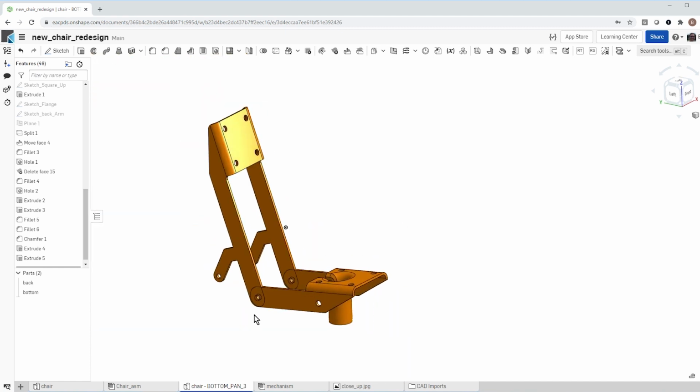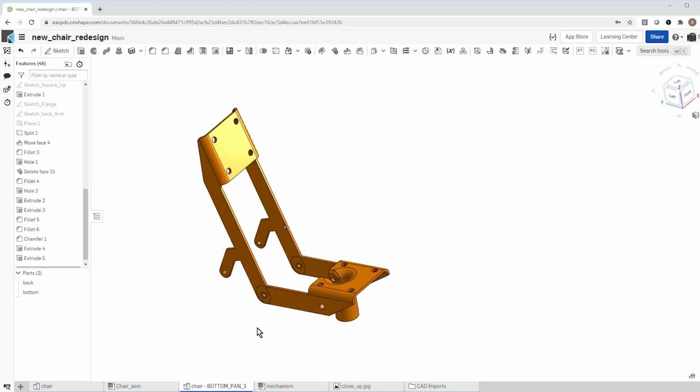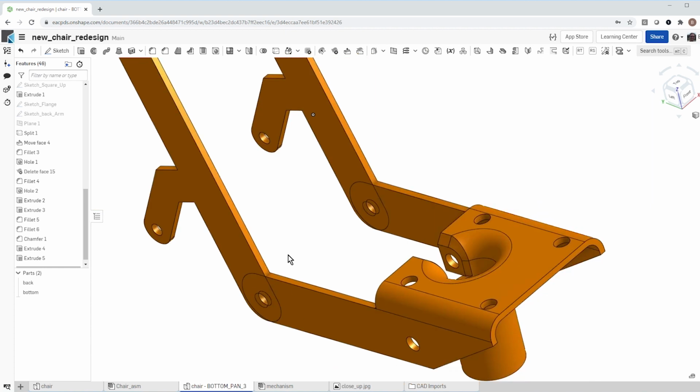So we can put in our piston, but the thing is that these guys are overlapping. I'm thinking about this, I could do a couple things. I could put maybe a little dog leg jog here on the inside part, or on this part going to the inside so it fits inside, or I can make this part and go either on the inside or the outside. But that would be another machining operation, another stamping operation, which would increase cost and things like that. So I'm going to use a different approach: I'm going to use this back part and actually make a part from it.